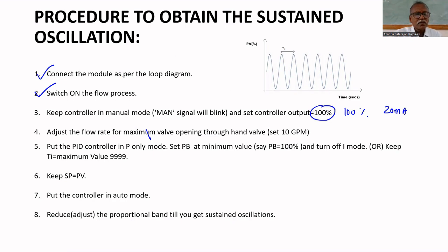Let us say in the lab there may be some deviations that they will tell you at the time of doing the experiment. Because sometimes it may be turbulent from 80% to 100%. That's why they will restrict to 70% of motor speed. If you go beyond 70, it becomes turbulent. The DP transmitter will give a constant value for laminar flow, not turbulent flow.